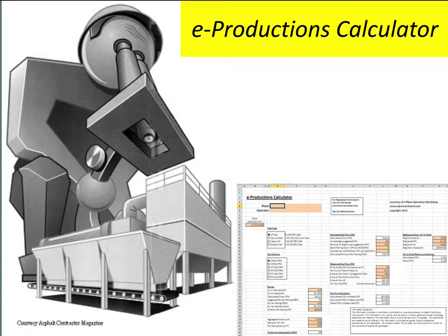The eProductions calculator is a spreadsheet that calculates the production rates one can expect by correcting the plant's equipment specifications to the conditions that it operates under. These production rates are calculated for different sized dryers, different sized exhaust fans which supply the combustion air, different gas velocities that carry away a certain amount of fines, and different fuels.